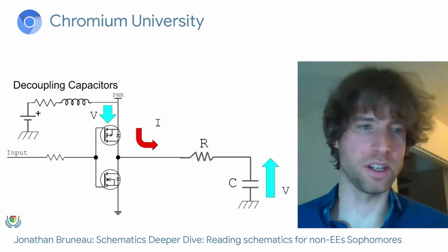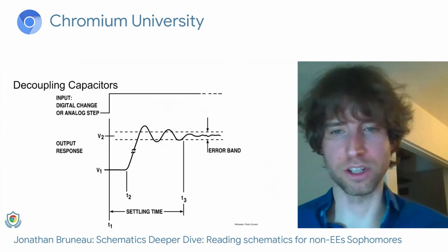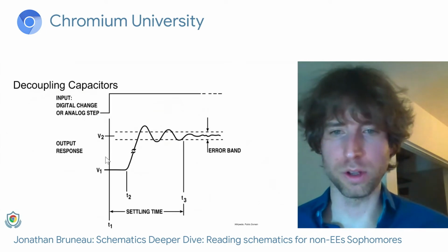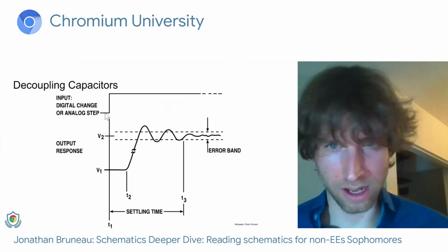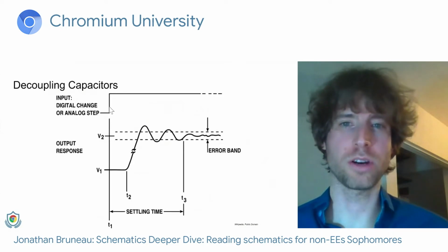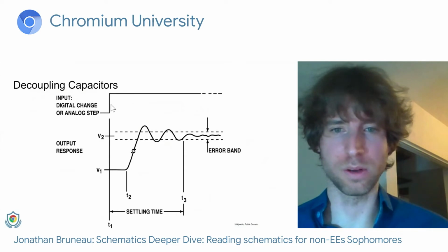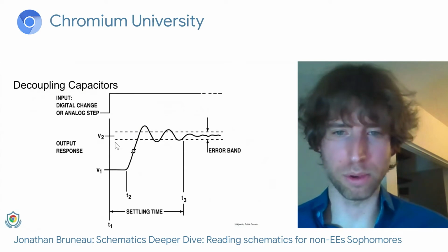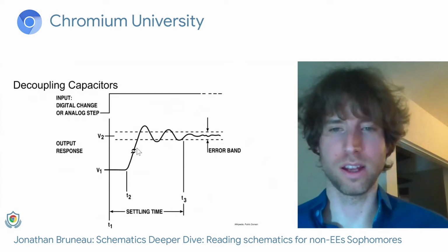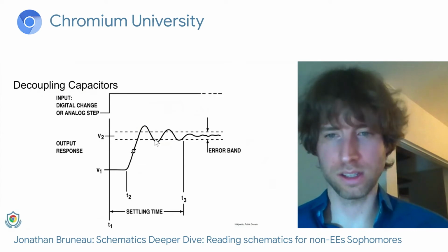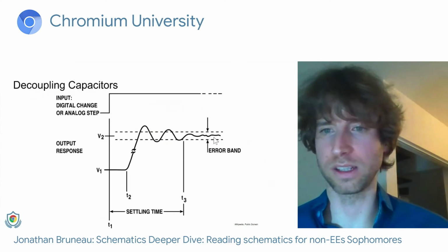And because of our parasitic inductance, I won't get into much of that, you don't get just a dip, you get a squiggle. So this is a diagram showing that if we have this sharp rise on our digital signal, and you were to probe the output on your oscilloscope, you would get a finite rise, and then this kind of wiggles around until it finally settles.